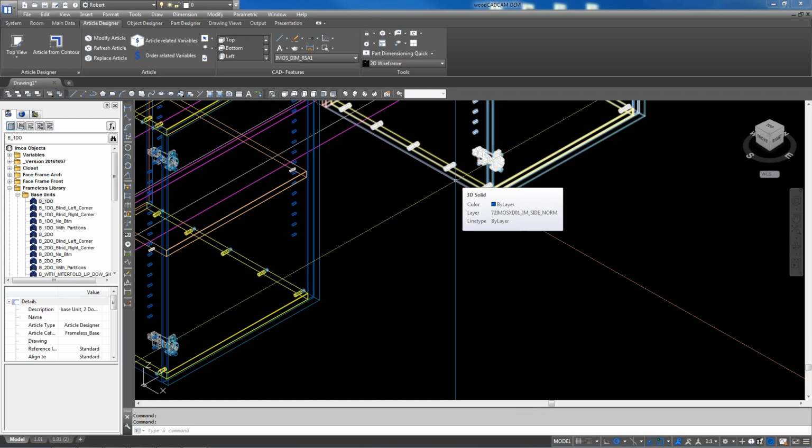Just have the one part with the slots already cut in it, and then if the opening changes and the slots grow, I'm assuming they stop like an inch or inch and a half from the end or something like that. It would fit between the other 2 bases with, let's say, a 1/32 gap on each side. Right, but you said it has 3 slots for airflow, so the slots would have to stop before we get to the end of the board, right? Right. So about 1.5 to 2 inches from the edges of that baseboard.